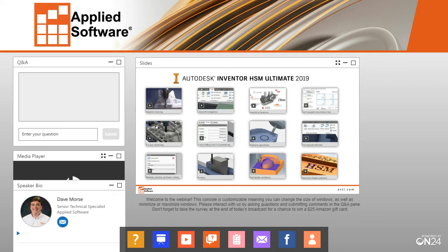Also, the support for any CAD inside of Inventor means that your source CAD files can update automatically to reflect your tool paths, even if they are not native Inventor files. So if they're Creo or SolidWorks or CATIA or any of these other, or even neutral file formats, if that file is updated and changes are made, the next time it's loaded, those tool paths are automatically updated.